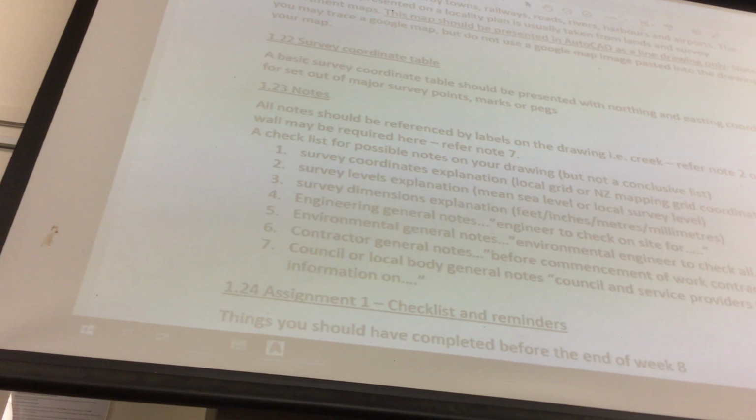And if they start from the manhole, they can then do a local survey and tie everything back to that manhole. Trouble is, manhole needs to be nominated something, so they might say, okay, let's make that 4,000 by 4,000 or 10,000 by 10,000. The reason why you don't make it 0, 0 is because your first bearing might end up as a negative number. So you try and have a nice big number right from the start.